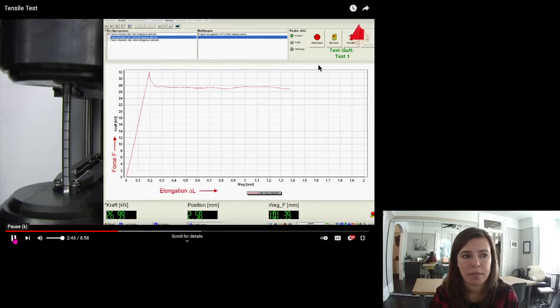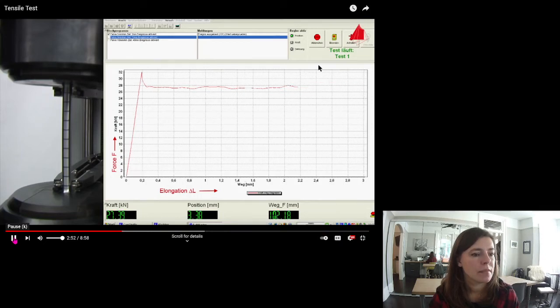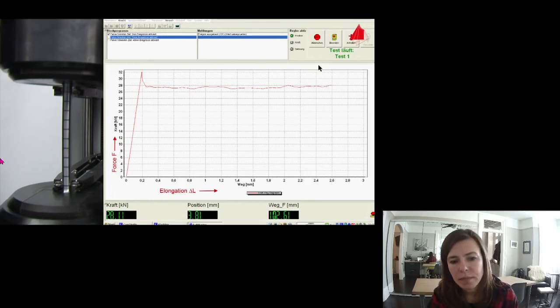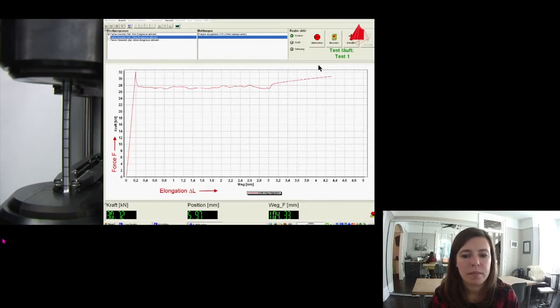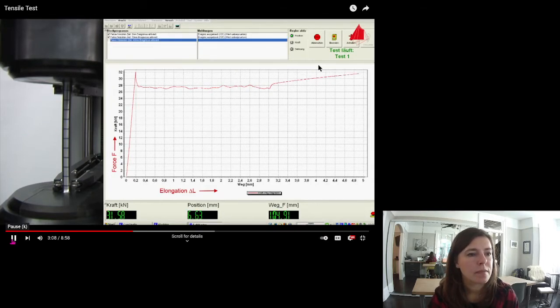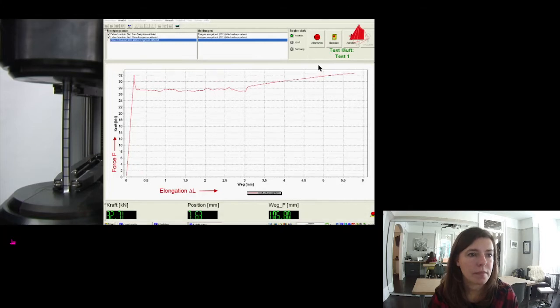In the next stage of the tensile test, an almost constant force level with slight fluctuations occurs. This phenomenon is called the Lüders effect. After a certain strain, known as the Lüders strain, the force increases again. The material opposes an increase in force against the imposed elongation. It strain hardens.